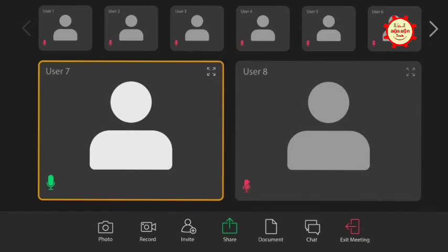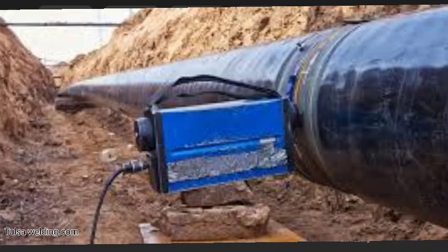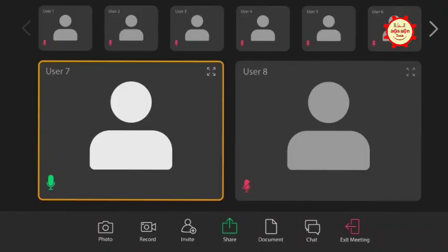Yeah, there might be, they are not able to put the film on that weld. To cover the complete weld, the RT film should be completely covered, and only then can they do it. If the film cannot be put on it, then they are not able to do that RT. That's why they might be saying that.